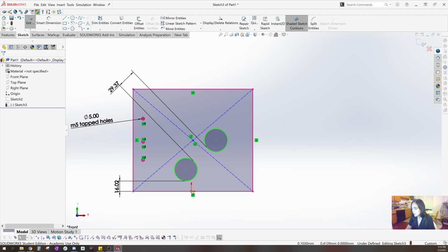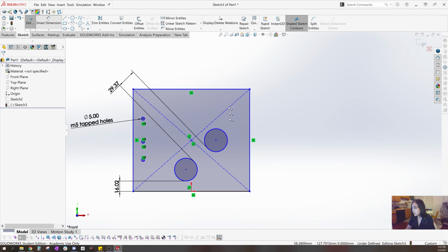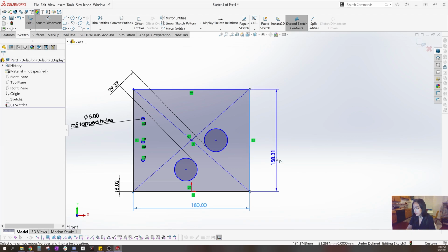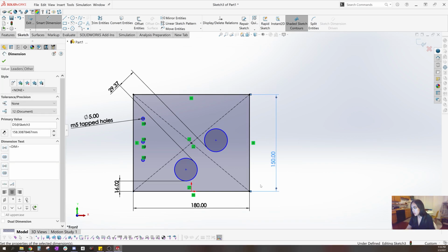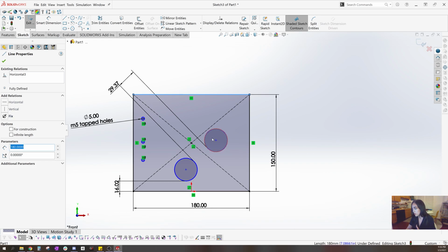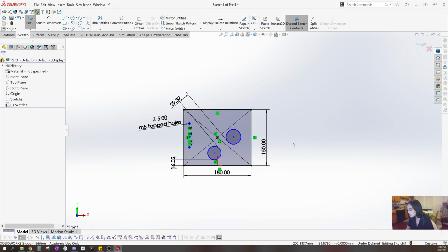Okay, so if we fully define the box, I'm going to have the box here on the midpoint of this line, midpoint there, and we do some dimensions. Whoa, all your beautiful colors just disappeared. That's problematic. Well, like I said, we can switch between the color mode versus the definition color mode, and that is this toggle here, color display mode. If I click that, I have my colors again. I can see what these colors mean, and if I want to see if my sketch is defined or undefined, I can click this mode, and you can see that the rectangle portion is constrained, and if I try to drag it, it's not moving around. Unlike these blue unconstrained things, you can see these are moving around and changing size.